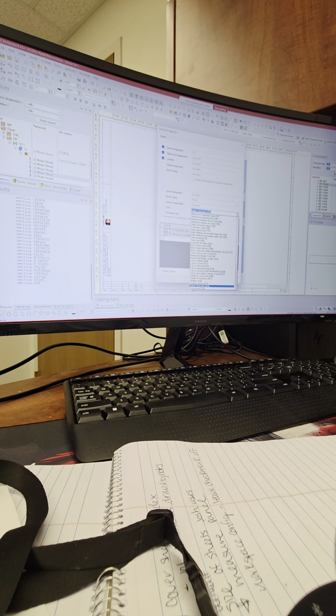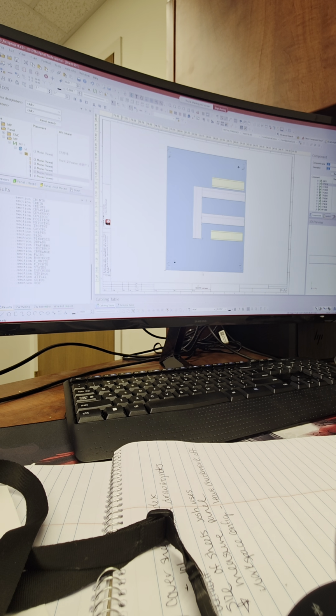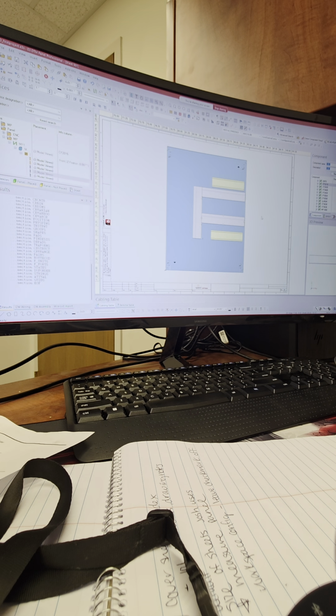Because you want to make sure that your wires are kind of mimicking the flow, how they are currently in your project. Right. If they just need to go from like a top rail to the bottom rail, like your picture showed, then you technically speaking only need one, right, between the two rails. One duct, I should say, just so the wires can go into the duct and then go left or right wherever they need to go, and then go bottom to the next rail. So let's just take your top rail and just move it slightly up, just so we're able to have a space to put a component on.